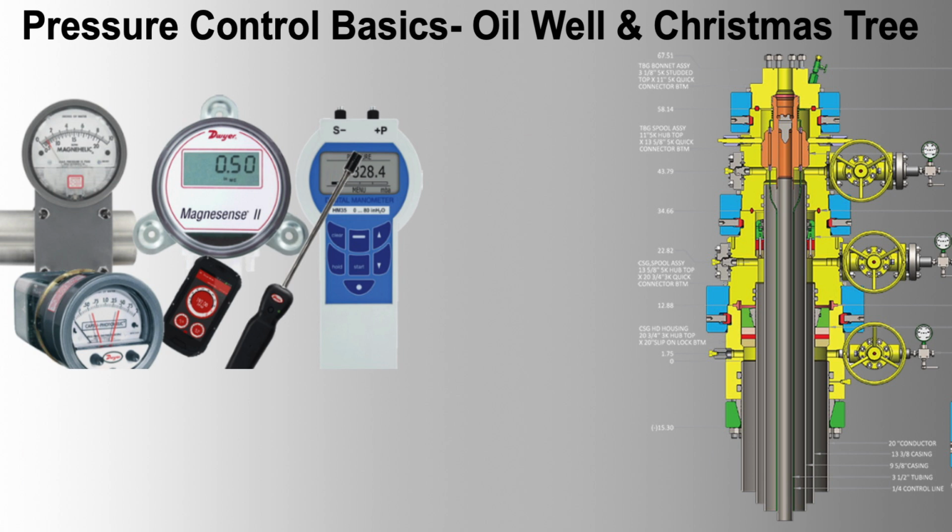3. Example 3, annulus pressure monitoring system. Instrument type, subsea pressure transmitter, accuracy, 0.2% of full scale. Material, duplex stainless steel for enhanced mechanical strength and corrosion resistance. Installation, subsea installation with protective enclosure and hydraulic tubing connection to the well annulus. Other criteria, 4 to 20 mA output, subsea connector with high IP rating, remote monitoring capability.